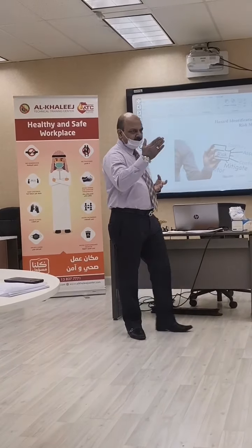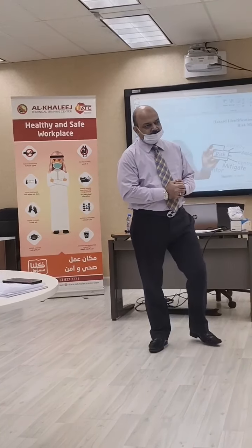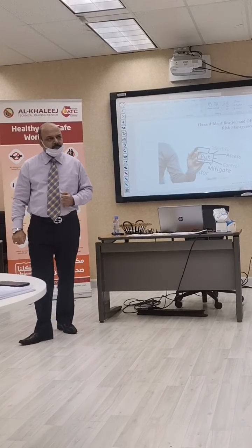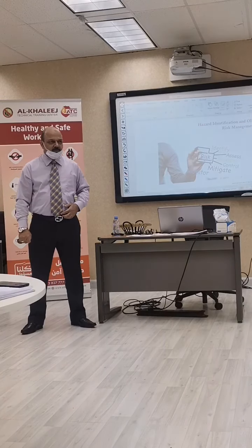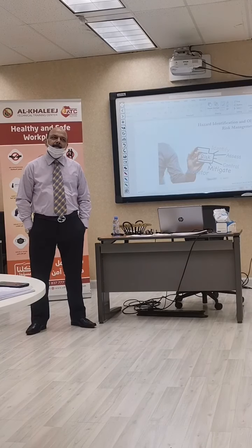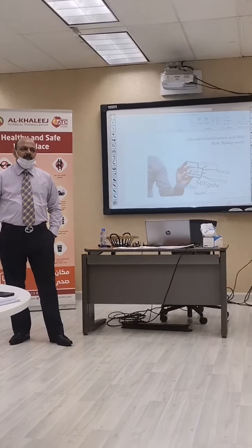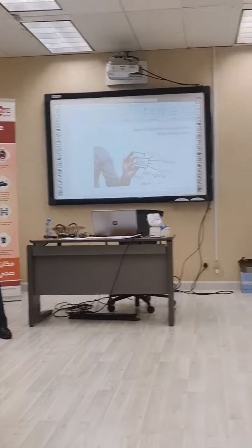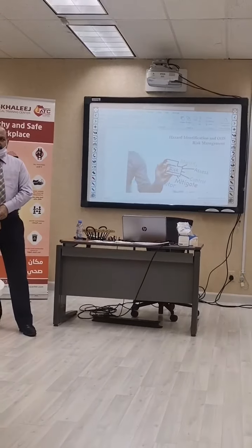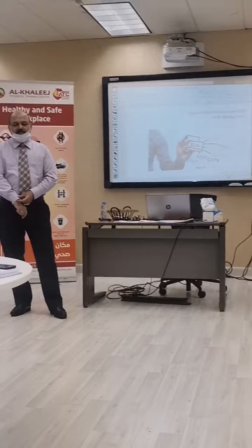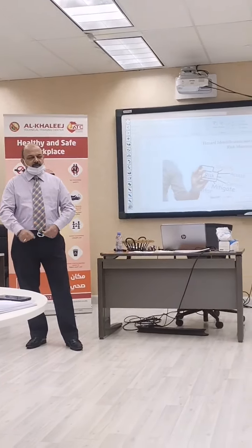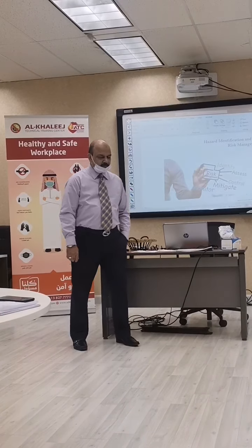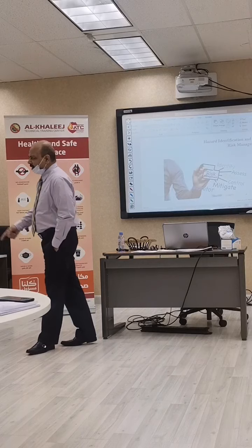What is the difference between correction and corrective action? Correction means we are eliminating the NCR, the non-conformity. But corrective action, we are overcoming the NCR that was issued to us. We are fixing the problem. Eliminating the problem is again correction. Corrective action is finding the root cause of that problem, so that it will not occur again and again.